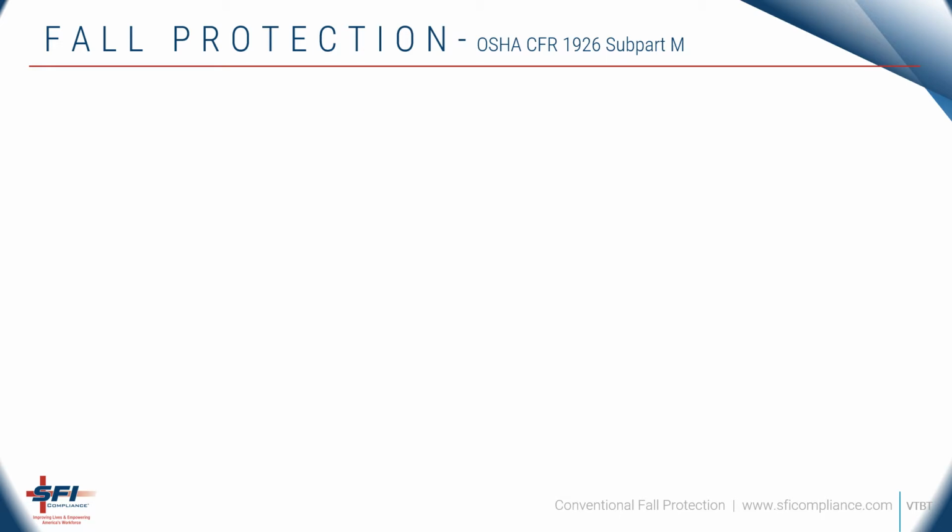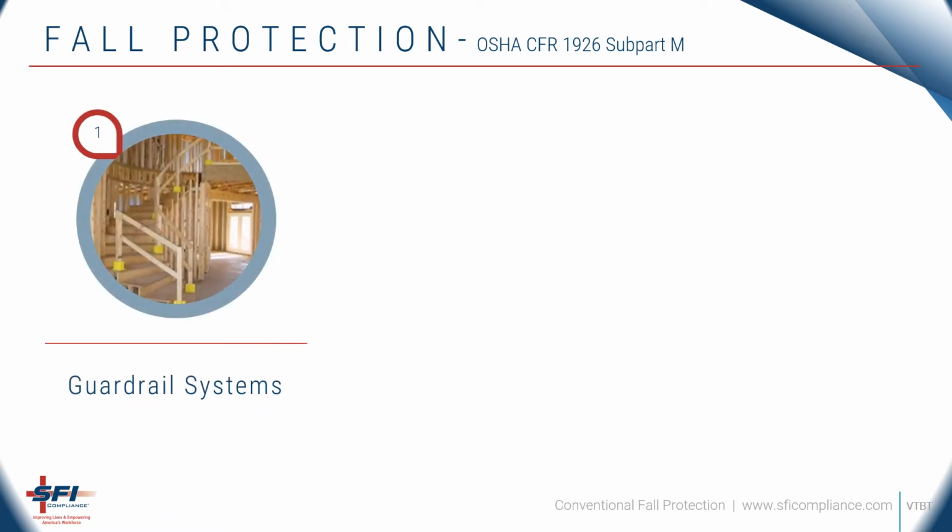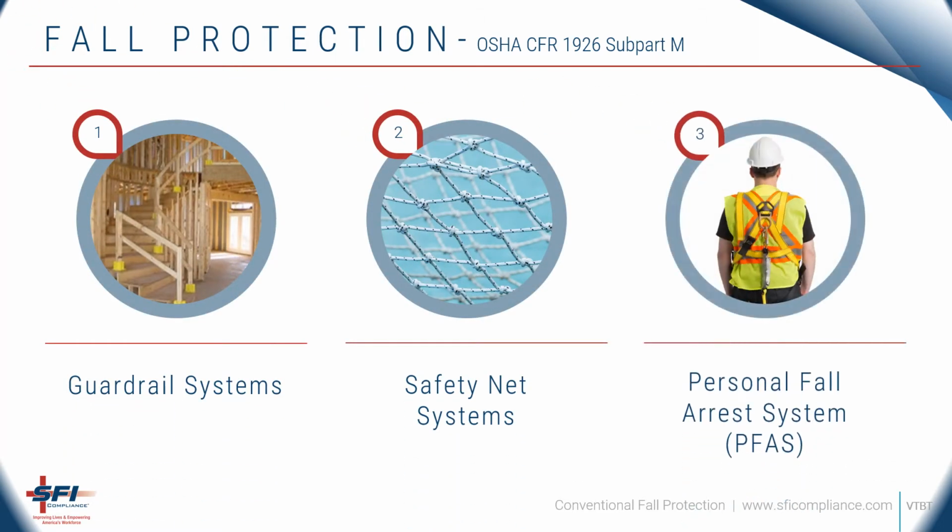The procedures specified in the standard are intended to prevent and protect employees from falling off, onto, or through working levels. There are three types of fall protection commonly referred to as conventional fall protection. These are guardrail systems, safety net systems, and personal fall arrest systems. It is up to your employer to determine which method is going to be used to protect employees exposed to a 6-foot or greater fall hazard.